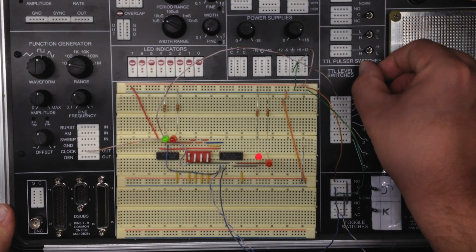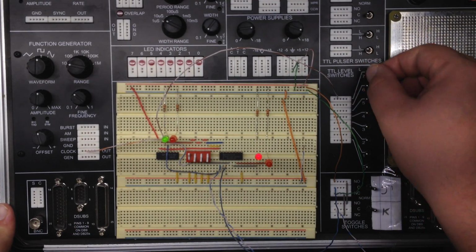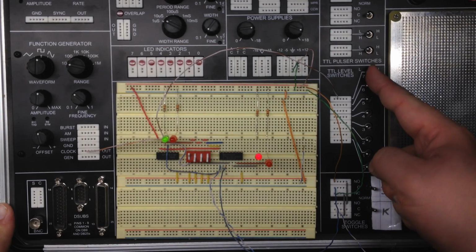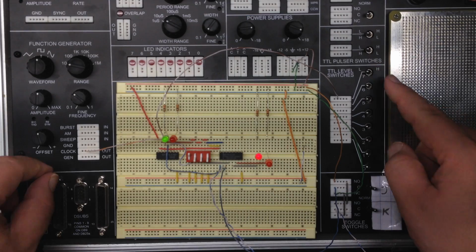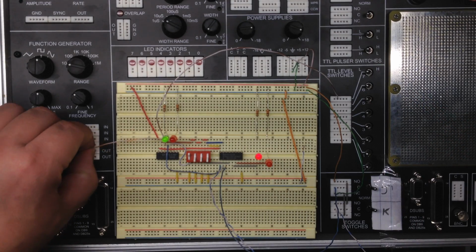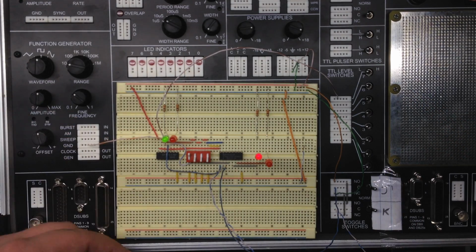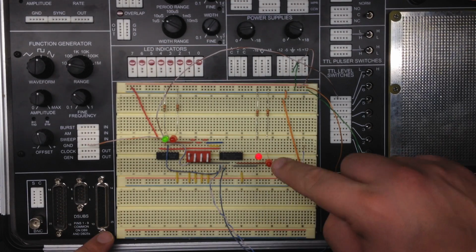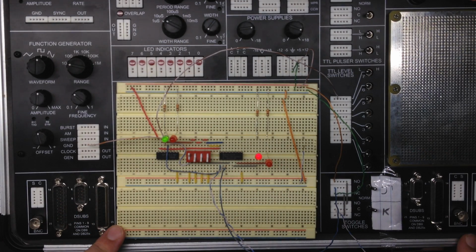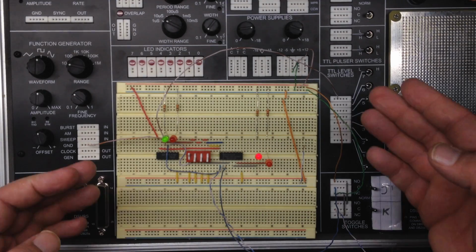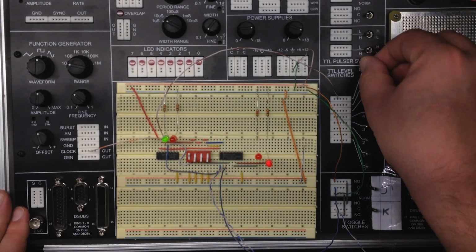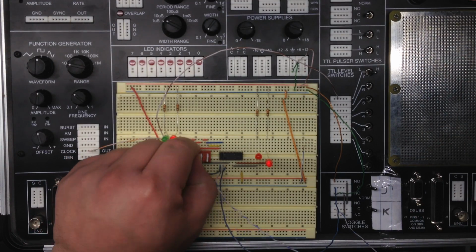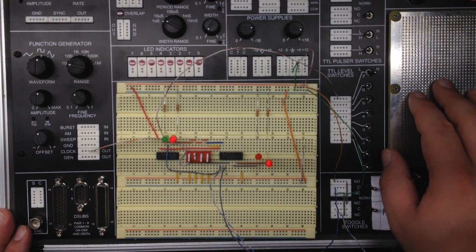We're going to change the state of our switches here. We can see that it does not matter whether our D input is high or low, and if we change the clock to a constant low, it still has no effect. We saw the toggle stop to show us that the clock has changed, but there's no effect on what happens there. We'll go back and demonstrate that with the preset as well.